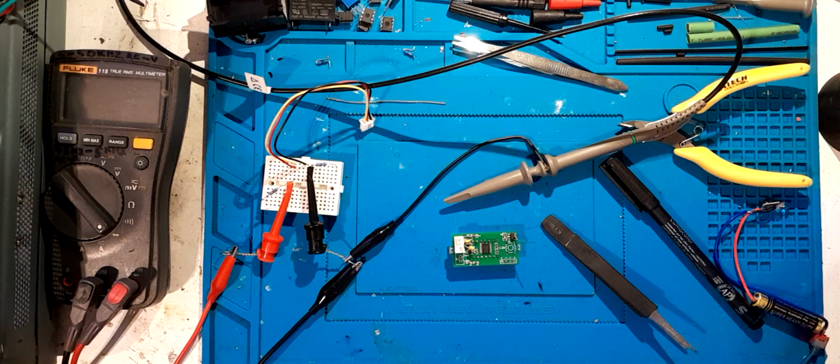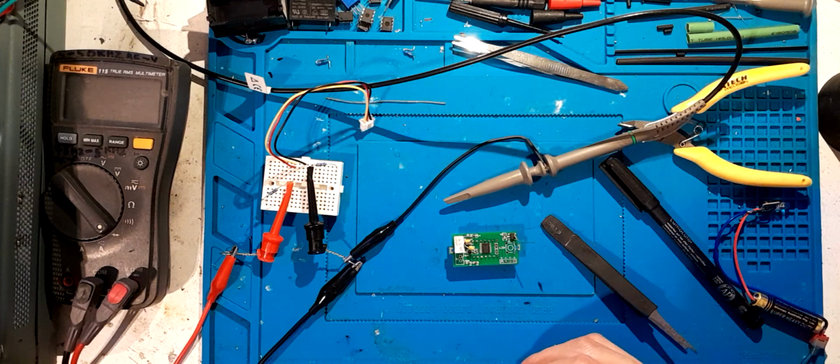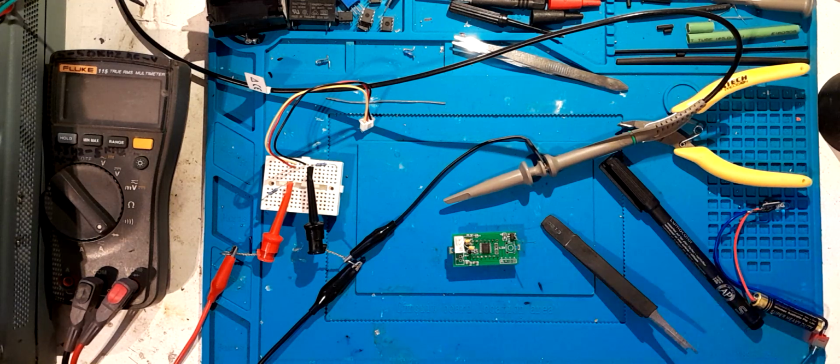Or noise, or oscillation, or ringing, or whatever it is. But what you don't know is that's actually leaking into your microcontroller, your op amp, and all of these different devices. They've got different common mode rejection ratios, power supply ripple rejection ratios. So what that means is they all leak a little bit of that noise inside them, into your measurement.